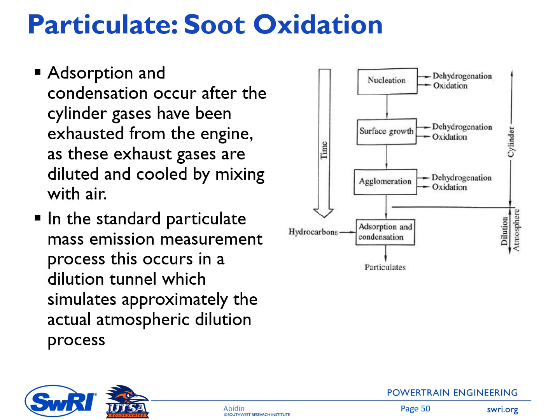And then in the exhaust system, we have absorption and condensation. In this case, the exhaust gas is diluted and cooled by mixing with air. So in the standard particulate mass emission measurement process, this occurs in a dilution tunnel, which simulates appropriately the actual atmospheric dilution process.